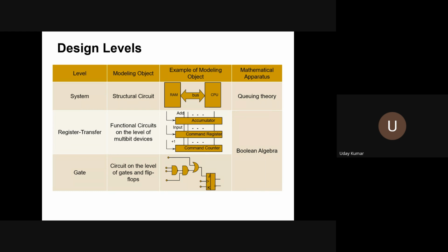So what type of bus do you want to use, a 64-bit bus, a 32-bit bus, or a 128-bit bus? The more the bit width, the more parallelism and the faster the fetch will be. Or else, if you reduce the bus width, then you need multiple cycles to get that particular data from that memory location and send it to the processor.